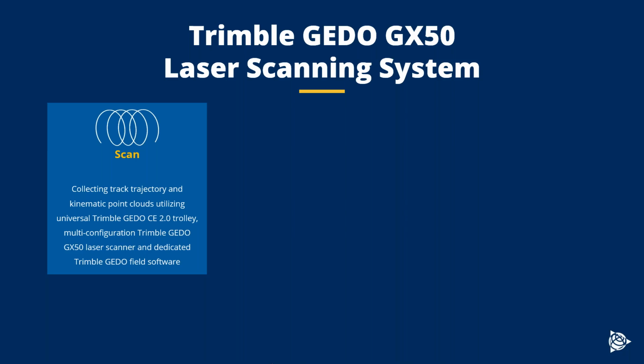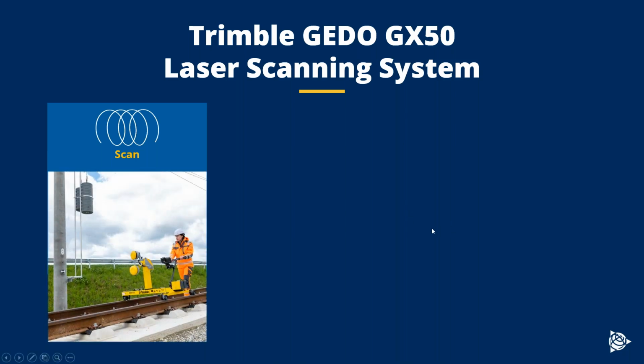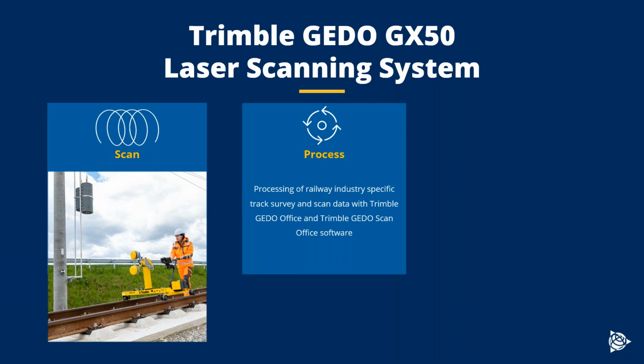We run the scanning. The process itself is not that complicated, and it requires little influence from the operator on the workload. Then when data is collected from the field, it needs to be linked together, because from the field we bring the trajectory and the point cloud data, and depending a bit on the system configuration, the process has to link them. In this processing phase, we have to link the trajectory together with the point cloud data.